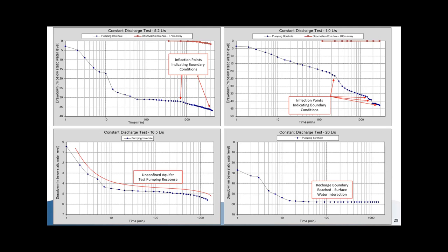So when we do the pumping test and we start pumping the water, and we confirm this later with chemical studies of samples of the water in the dam, we start abstracting water from the groundwater. And as soon as there's a pressure gradient to draw water back towards that borehole, the dam starts leaking into the groundwater over there. And so this means, in essence, if we use this borehole and pump it to the dam and use the dam to supply irrigation or a town or something like that, all we're doing is just recycling the water around and around between the dam and the borehole, which is not very effective at all. So that's another interesting thing to know.